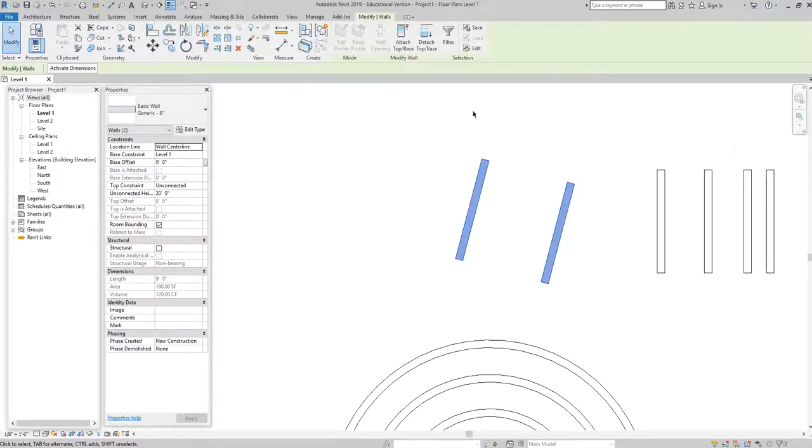So if I just type in a positive number, it's going to rotate, or no, sorry, that's not right. Revit still really plays on the right-hand rule, where if you type in a positive number, it goes counterclockwise, and if you type in a negative, it goes clockwise. But with that said, I moved my cursor this direction, which overrode that positive negative direction. And I think that's just easier, right?